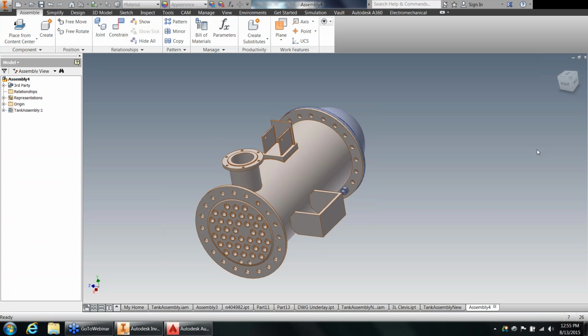All right, so over the last hour, we've gone through a number of the different workflows that are directly related to the AnyCAD acquisition and functionality that's been embedded inside of Inventor, as far as bringing in a DWG underlay and utilizing that geometry and seeing it update when the AutoCAD file is saved, importing SolidWorks documentation into the Inventor space, selectively deciding which components thereof we want to work with, and then seeing it change live when the SolidWorks file is updated.